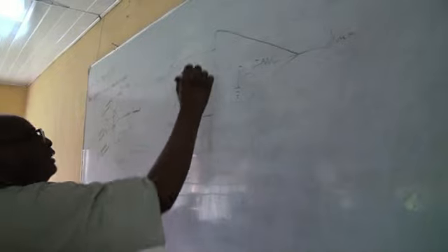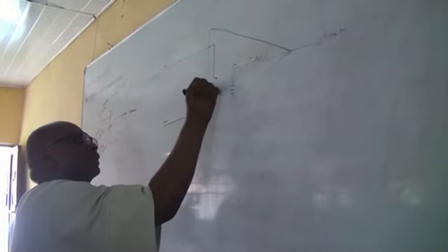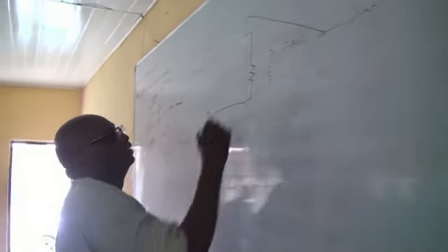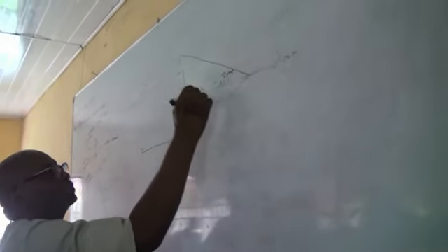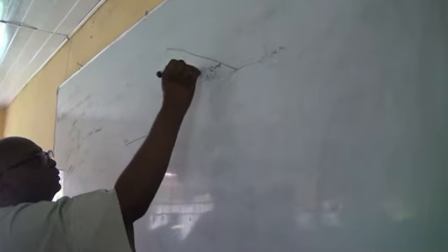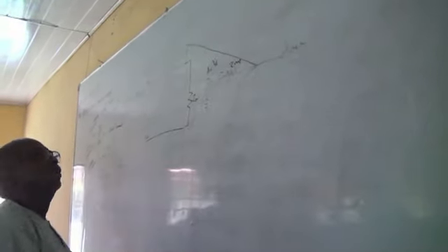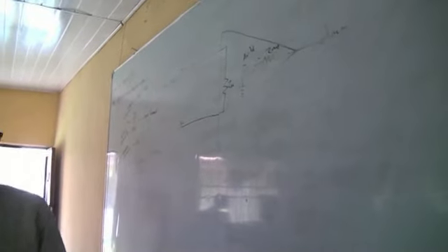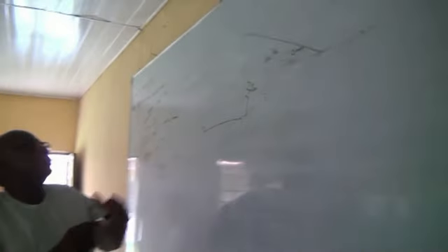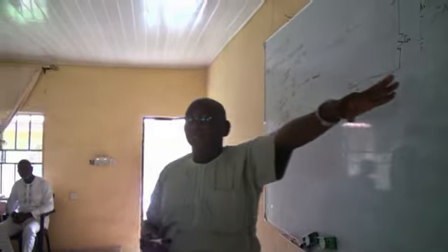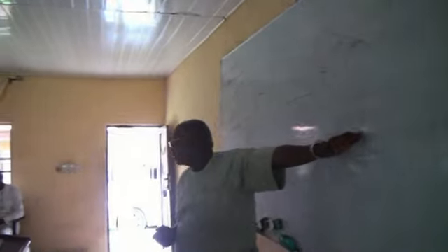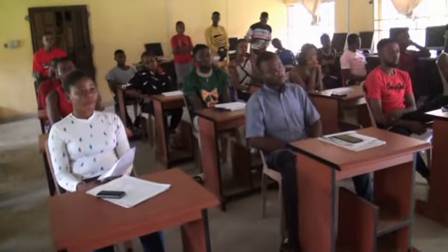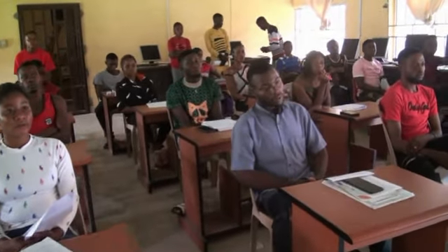Yes. Okay. Then here, inside it, you have a resistor connected again, which is called Z in, and this one Z out, and this one is a voltage gain, with VD, the differential voltage. The reason we say differential voltage is that the difference between the voltages V1 and V2 determines the function of an op-amp. Yes, the difference between V1 and V2 determines the operation of an op-amp.